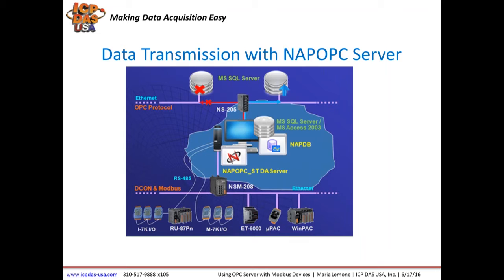NAPOPC Server supports multi-thread communication, so there's a different socket used for communication with different devices. It helps streamline and speed up communication so each individual piece of equipment can be polled based on requirements. NAPOPC can be run on a PC or one of our PAC controllers.